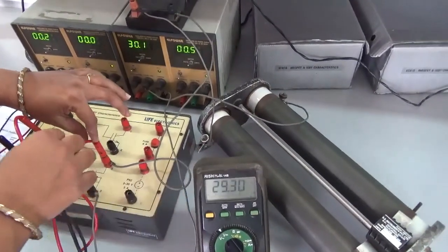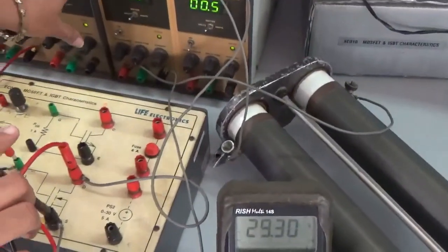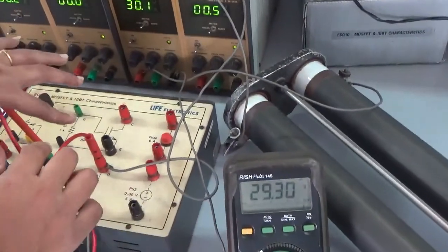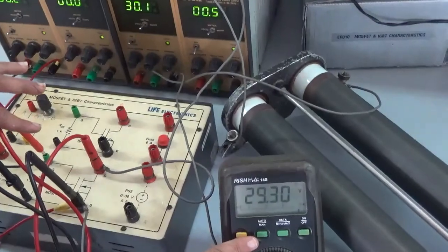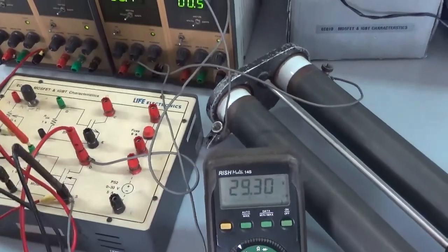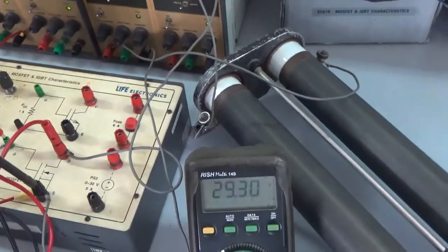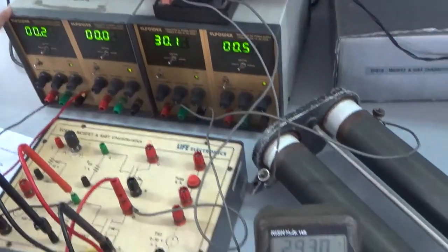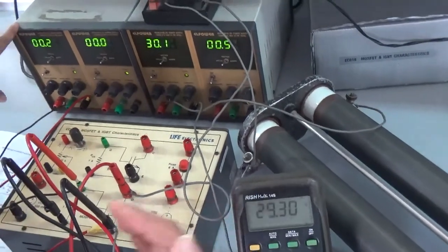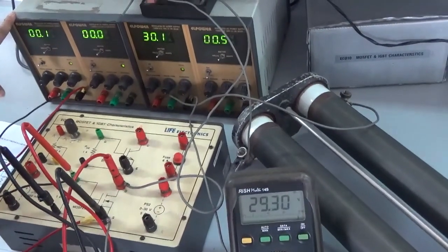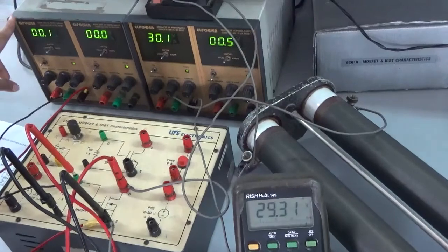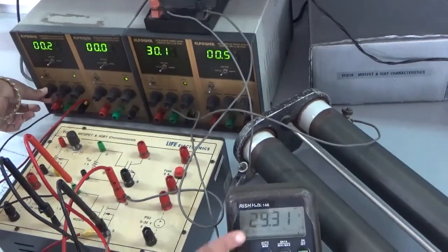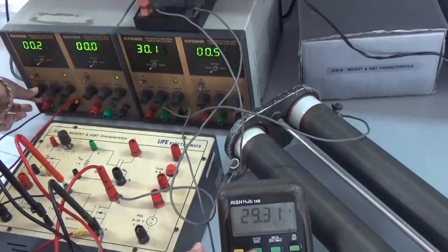This indicates the MOSFET is in off state. So the entire supply voltage we are giving to the MOSFET is appearing across the MOSFET itself. This multimeter VDS shows this value. Now what we need to do is vary VGG until the value in this voltmeter drops exactly to half of the voltage. So I am going to vary PS1, that is VGS, until this value goes to half of it, 50% of this value.